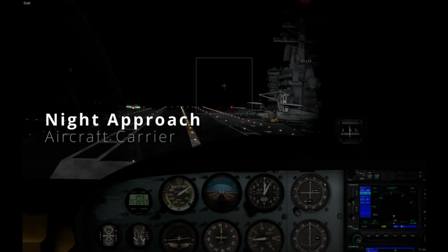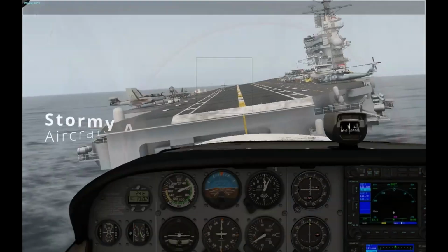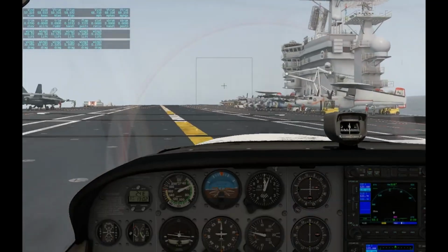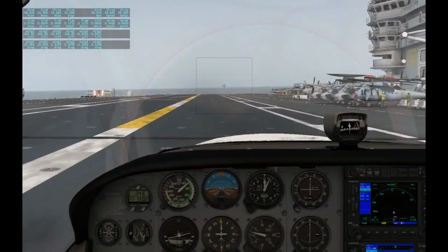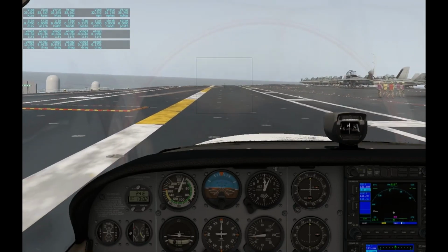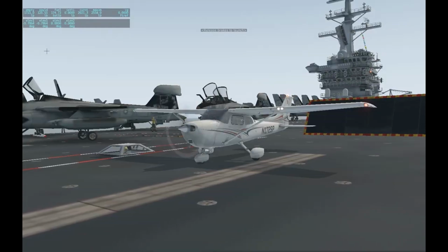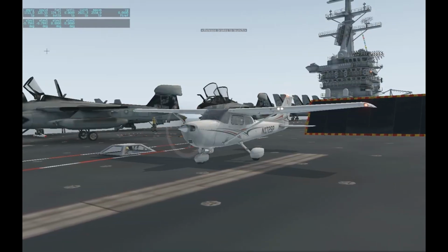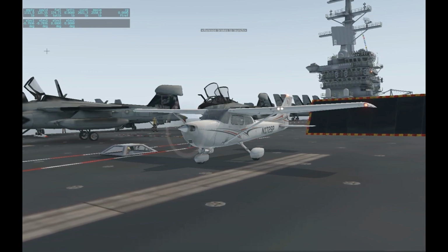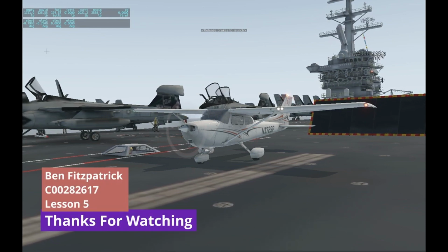And finally, we have some carrier landings with different landing conditions. Remembering that the purpose of lesson 5 was to understand how flaps can affect the landing, that by utilizing throttle control you can control an aircraft's airspeed during the descent and during the approach phase, and also by utilizing the PAPI system you can land the aircraft at the correct point of the runway, remembering that for an optimal landing, 2 red, 2 white, all red lights you're too low, and all white lights you are too high.